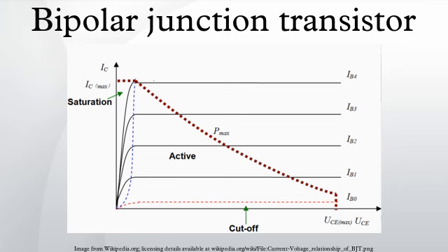Heterojunction bipolar transistor. The heterojunction bipolar transistor is an improvement of the BJT that can handle signals of very high frequencies, up to several hundred GHz. It is common in modern ultra-fast circuits, mostly RF systems. Heterojunction transistors have different semiconductors for the elements of the transistor. Usually the emitter is composed of a larger bandgap material than the base.